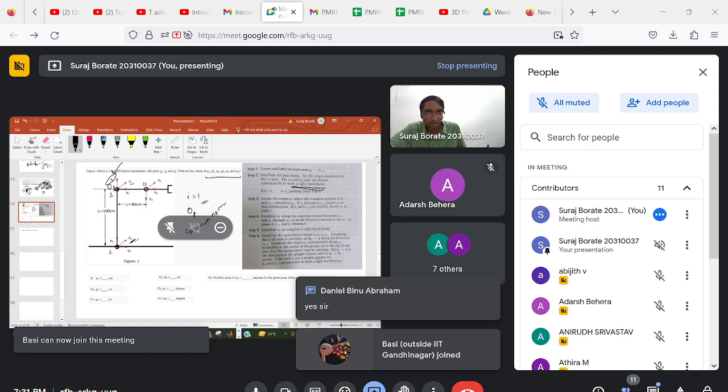So common normal between Z0 and Z1. This is Z0, this is Z1. This is the common normal, right? Z1 is going into the screen, Z0 is also going into the screen, so this normal is on the screen. For two parallel lines, the common normal will look something like this. There are infinite number of common normals, but for convenience we are putting it on the link itself.